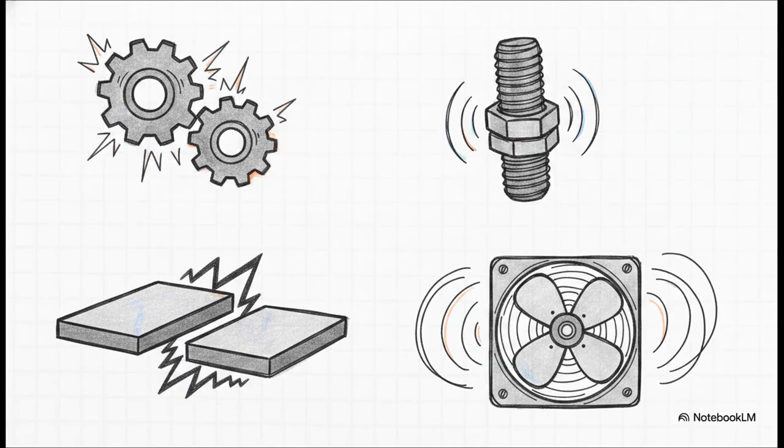In industrial environments, we use a pretty extensive troubleshooting guide to identify these issues. Vibration is often caused by those repeating forces or looseness we just talked about, but it can also come from resonance or sharp impacts like gear teeth meshing together. One super common trigger is the impact generated by rolling elements repeatedly passing over microscopic flaws in a bearing raceway. And we absolutely can't forget randomly generated turbulence forces. These are a massive headache in rotating equipment dealing with fluids and gases, like industrial fans and blowers.